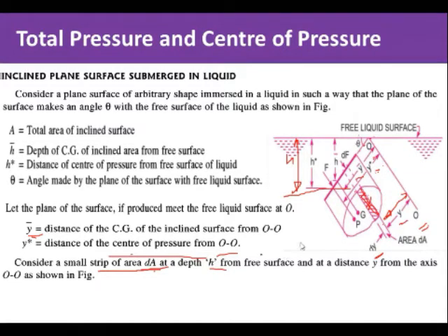After that we consider the hydrostatic law. What this hydrostatic law states: if you consider any fluid particle on the liquid surface, the pressure acting is atmospheric pressure, PA. And if you consider any fluid particle at a depth z, the pressure at depth z is rho g z.